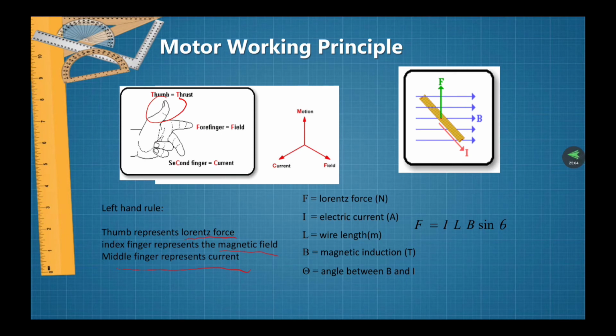When the armature winding is connected to the DC supply, for example in a DC motor, and electric current is set up in the winding, the permanent magnet or field winding electromagnet provides the magnetic field. In this case, current-carrying armature conductors experience a force due to the magnetic field.